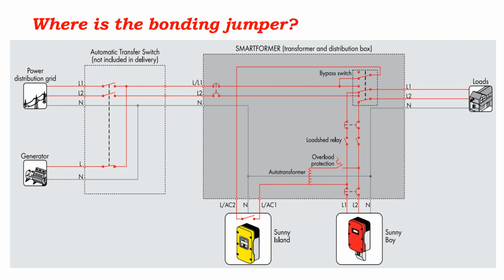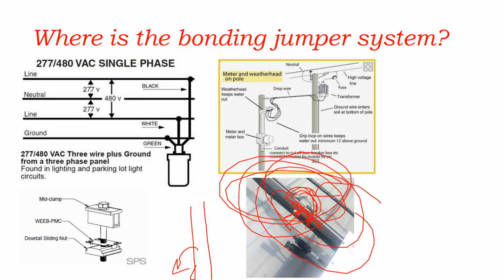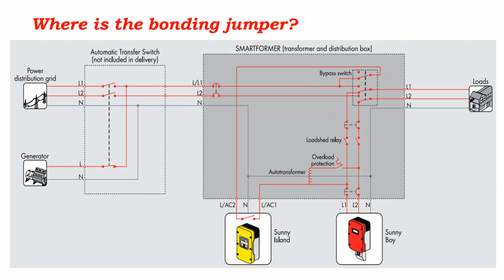And it used to be in old school solar design, you would actually run copper throughout the entire array and connect every single module onto the copper conductor because the rails were not listed as a ground path. Now the rails are listed as a ground path, but you have to use a specialized little jumper to ground your rail-to-rail connection.